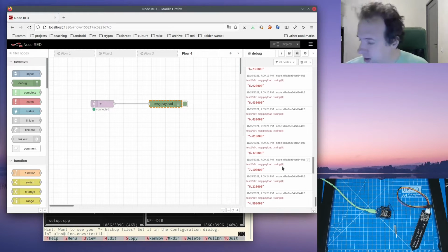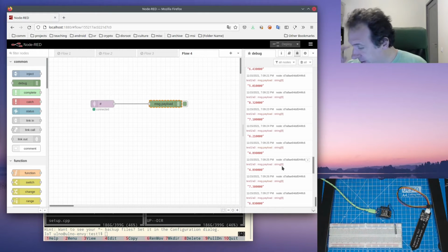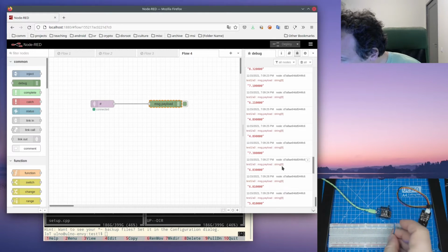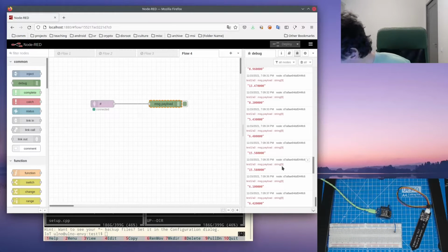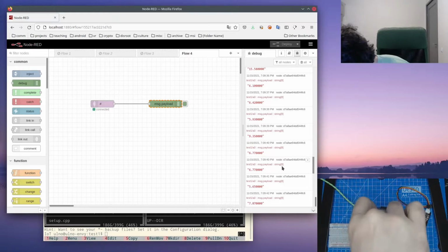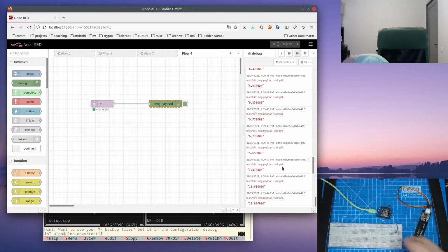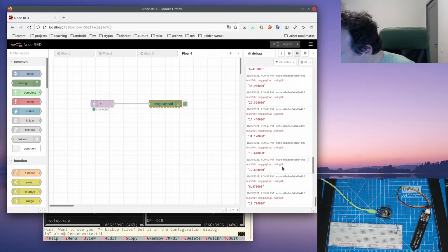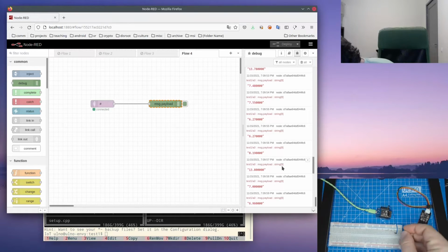And then you can connect it via a voltage divider. So let's get the signal out somewhere here. Basically we will feed the output signal through a resistor. I take here a 10K resistor, 10 kilo ohm. Then we feed the output signal there, and the other side here we'll put against ground.